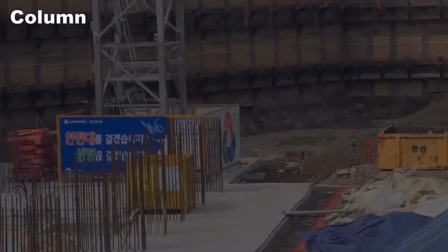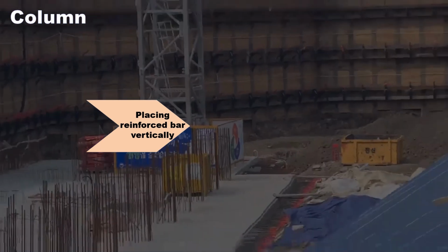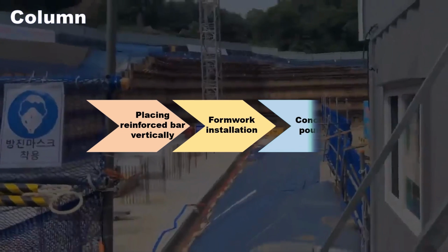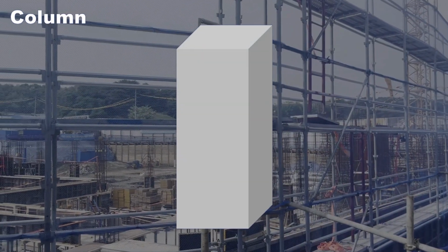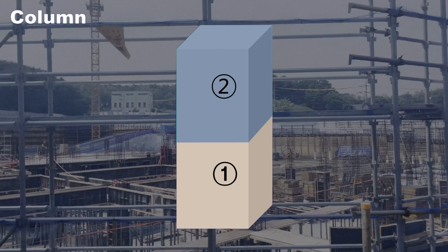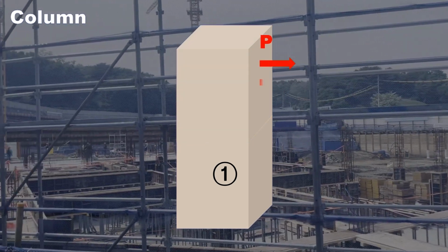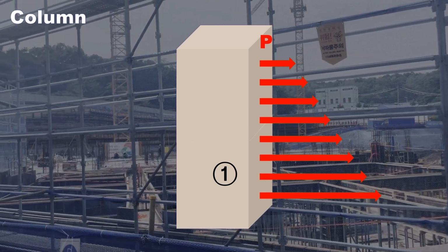The column installation process can be divided into three main steps: placing the reinforced bar vertically, formwork installation, and concrete pouring. The important thing to note here is that the concrete is poured in two steps to prevent the pressure generated by the concrete when it is poured into the formwork from being too high and causing the formwork to burst.